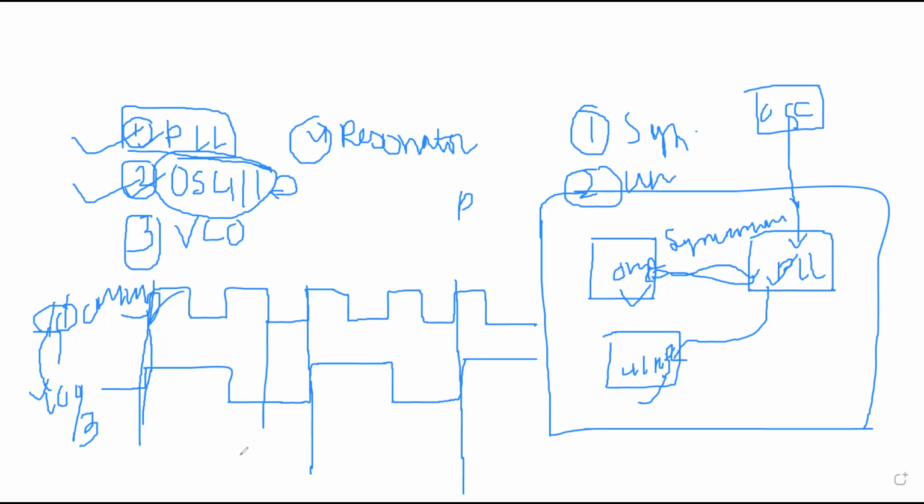Okay, so we can compare the phase difference by comparing the posedge of the clocks. Let's suppose we are working on any posedge. Take any posedge, compare it, and if this aligns, we can say they have a 0 phase difference, or a 360 phase difference. So can we tell whether 100 megahertz and 100 by 3 are synchronous clocks or not?